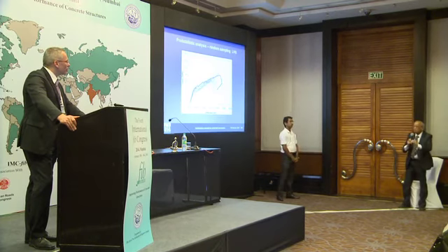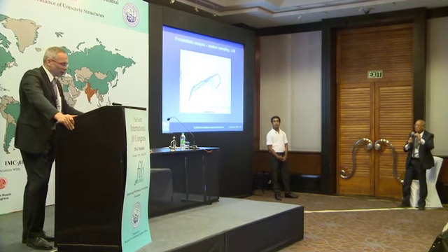Sir, if you are using the plate element or something, it doesn't use all the degrees of freedom. It uses only a few degrees of freedom. It's not a real estimate of what happens. Therefore, a bending analysis which is quite correctly producing bending moments or something using one type of element is not necessarily representing the other effects quite effectively. And in that sense, mathematics is inadequate. For bending elements, it gives only that particular type of solution. Yes, that's why I was mentioning.